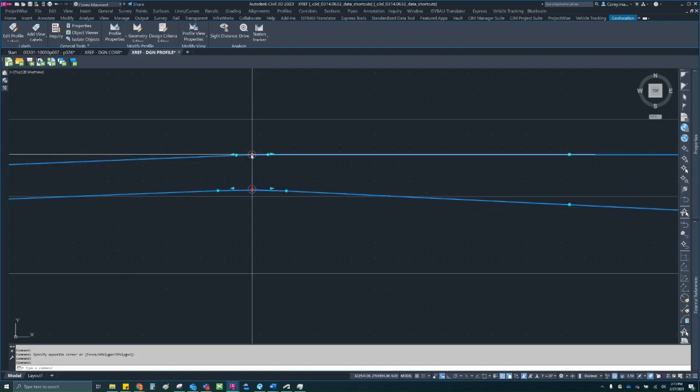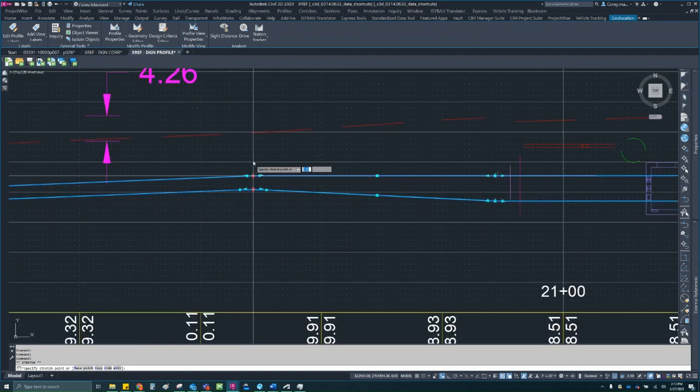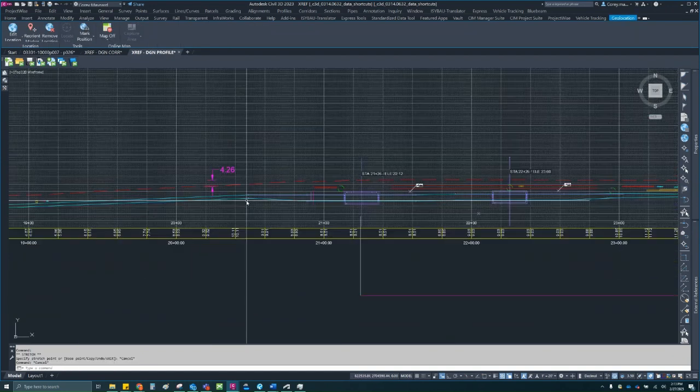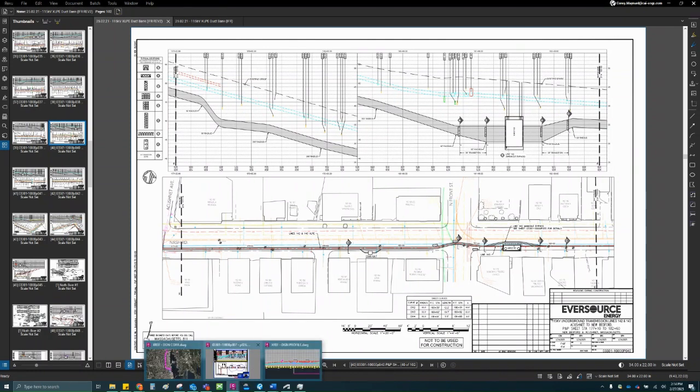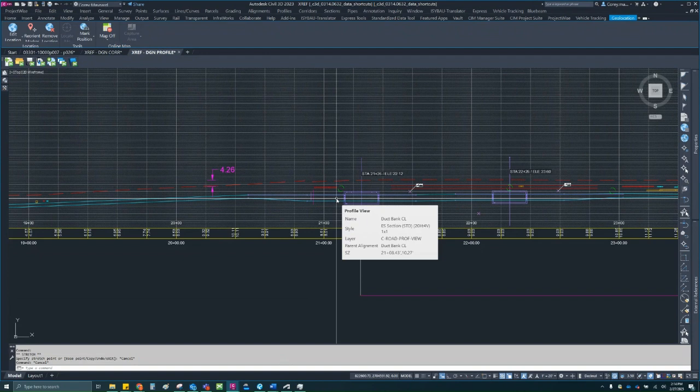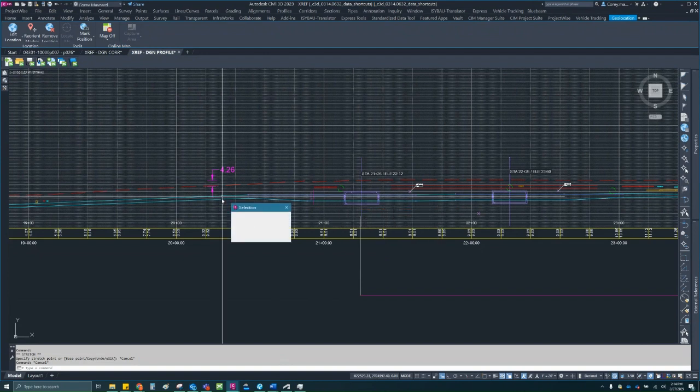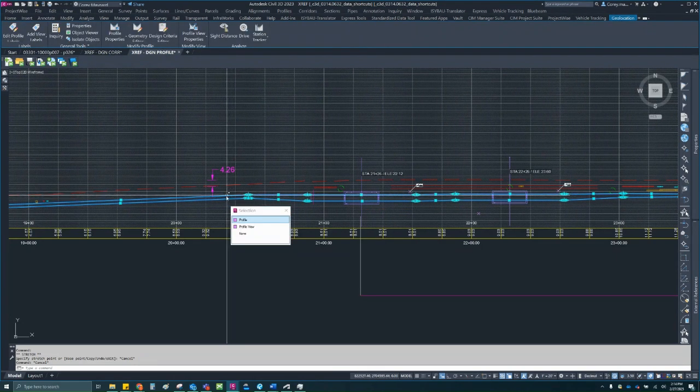Both the top and bottom will move in unison. And this will affect everything in all drawings, in all sheets throughout the entire project, even though these sheets are not being created from this base design drawing. This is just where the profiles are being shortcutted from.